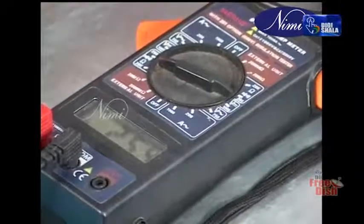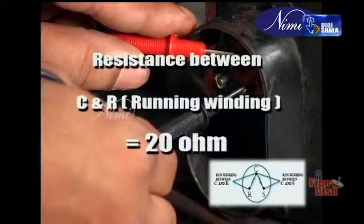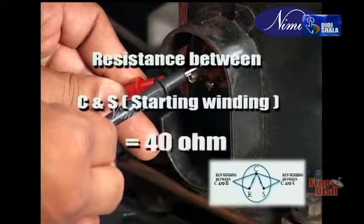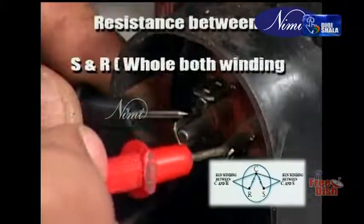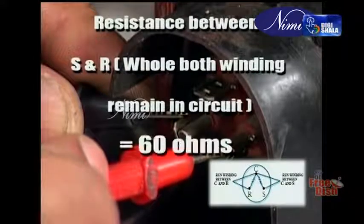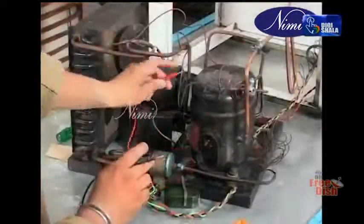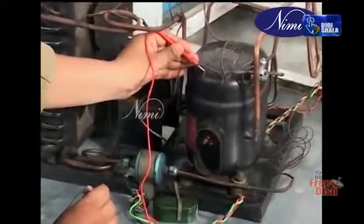Summarily, we found that resistance between C and R, the running winding, equals 20 ohms, and resistance between C and S, the starting winding, equals 40 ohms. And we found resistance between S and R, where both windings remain in circuit, equals 60 ohms. By this exercise, we can search out the running and starting terminals.